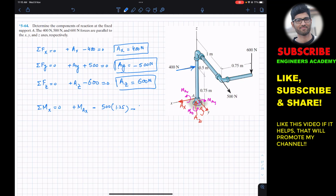We will write 600, and the perpendicular distance of this 600 Newton force from the x-axis is this 1 meter distance. So this is the moment arm of this 600 Newton force from the x-axis. So I will multiply this with the 1 meter distance. This will be equal to 0.